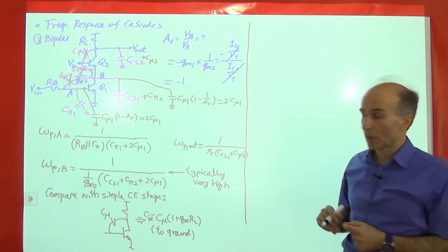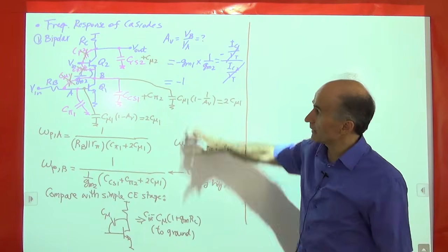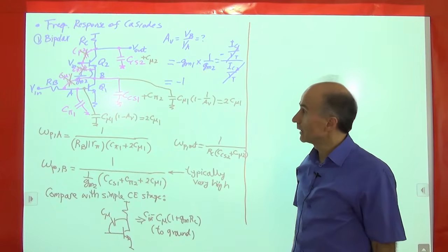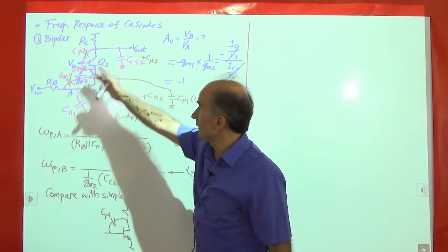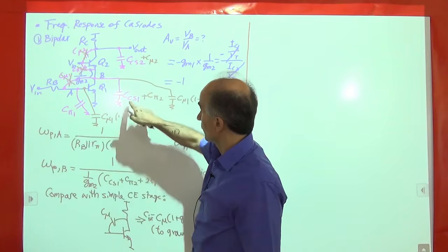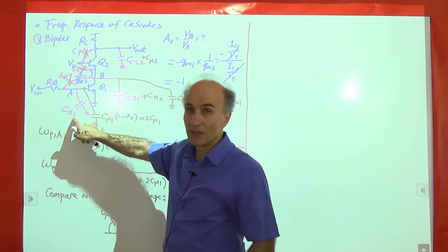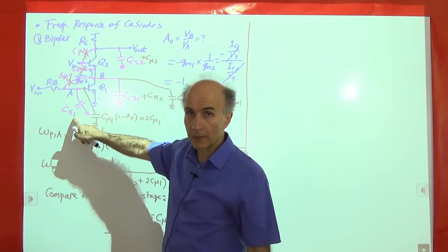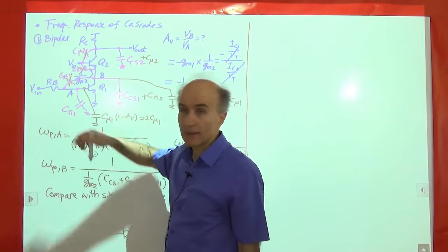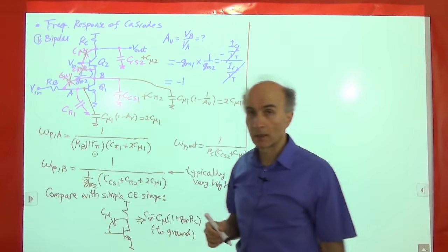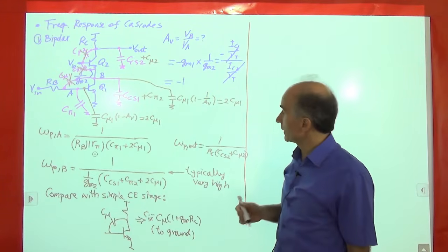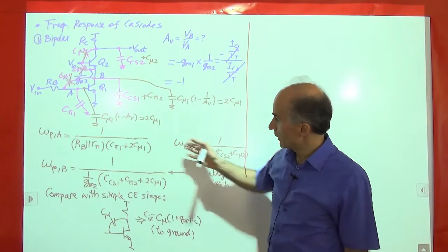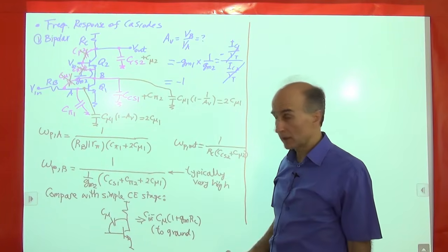All right, now we go to the MOS version. The MOS version is very similar, so I'll just skip all of that. You have all the capacitances, everything here. Of course, this is now called CGS1, not C pi 1. But it is also very similar, so we won't really deal with those that much. All these equations are approximately correct there.